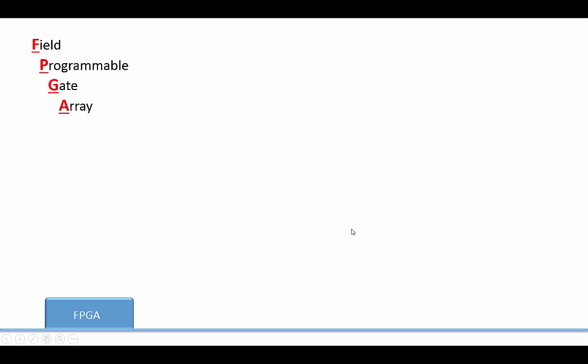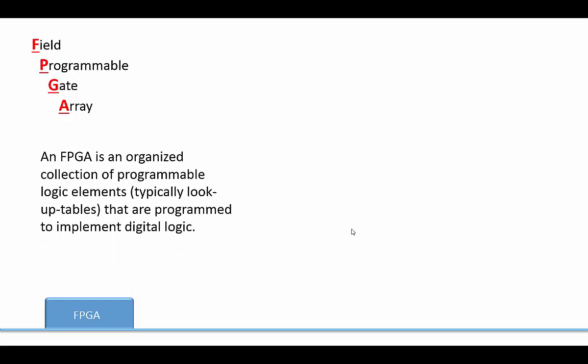Welcome to Field Programmable Gate Arrays, better known as FPGAs. An FPGA is basically a lookup table that you will program via software. So we'll take a collection of inputs that we have and determine the desired outputs and then program that into a device via some software. We'll either use schematic entry or a hardware description language.